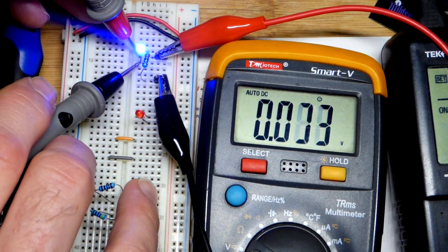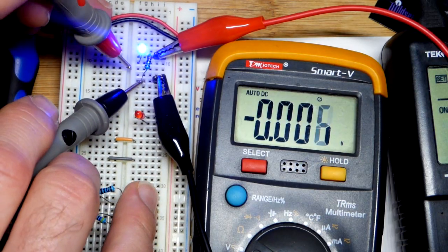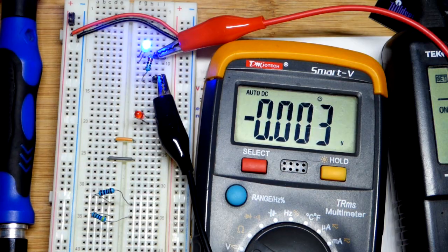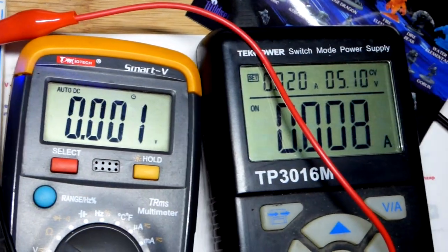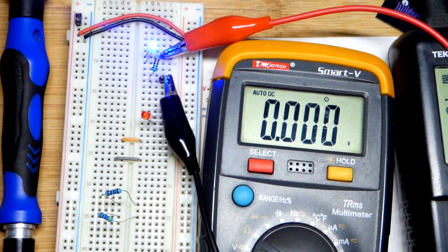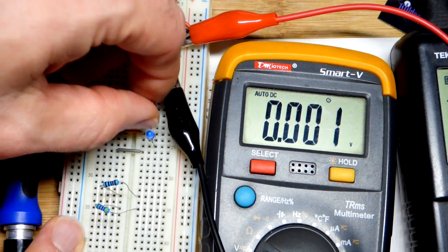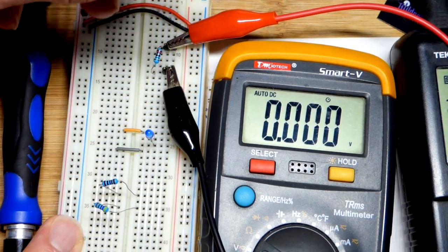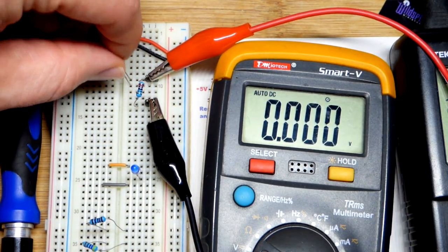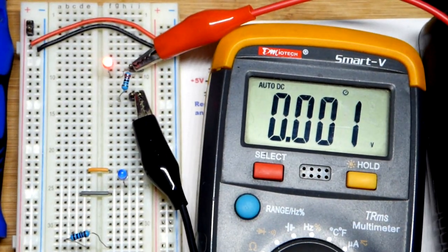So blue LED, as I said before, drops about 3 volts right there, leaving about 2 volts across the resistor. So that's a fair amount of voltage lower than we had with the red LED. So we got about 10 milliamps of current flowing. There's less voltage across the resistor, so less current. We can just pluck the blue LED, grab the red LED, and put it in the place. So again, we got to put the longer lead, the anode, towards more positive, shorter lead, the cathode, going to the resistor, and now we have a complete circuit.